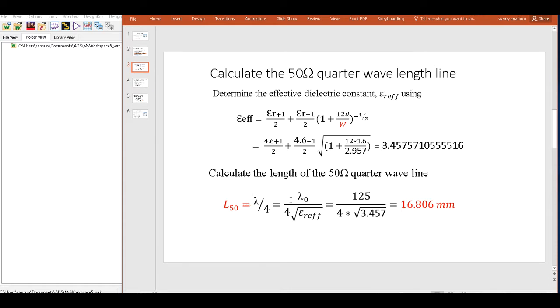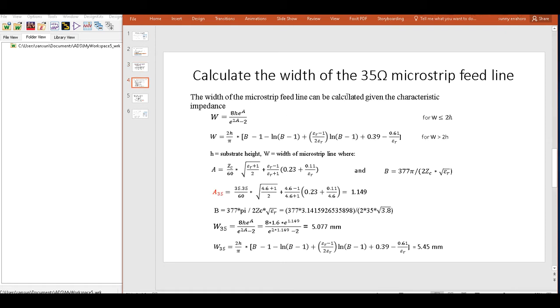So we now put that 50 ohm value in to find our quarter wavelength, which is the value of our wavelength, which we obtain from the speed of light divided by the frequency. That gives us the wavelength. So doing this multiplication too, we arrive at the length, the quarter wavelength of the 50 ohm section, to be 0.806 mm.